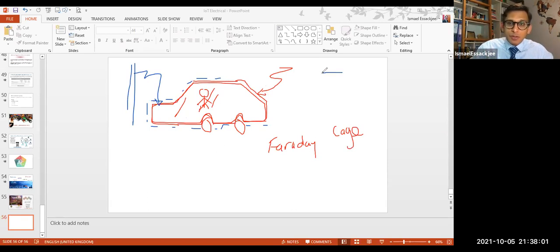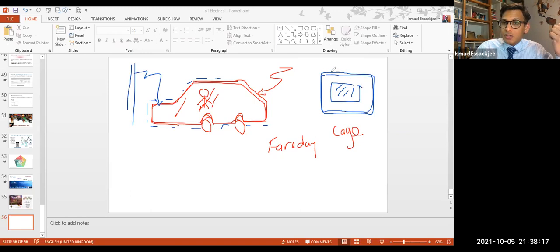So if you apply the same philosophy, you can have what you call a Faraday cage. You have your equipment in a box with metal casing, and all your things are there: your sensors, actuators, antenna. I don't know if you need to have the antenna outside also, but this is going to protect it. If there is a lightning strike, only the outer part is going to have this extra charge, but inside everything is going to remain safe.